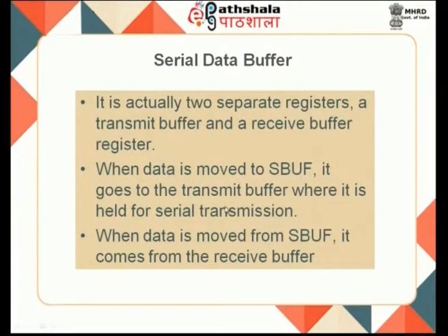Okay. So, when data goes to the SBUF, it is the transmit buffer, which holds the serial transmission. When data is moved from SBUF, it comes from the receive buffer. So, the SBUF is the interface between the serial transmitter or receiver of a serial communication and the processor.